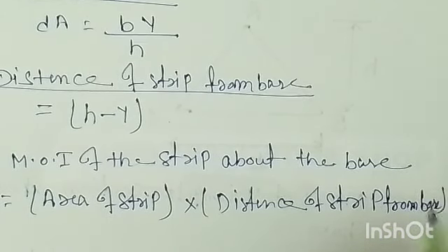Now when you multiply by b, first you can see that h to the power 4 is everywhere, so we can take it common and take it out. So this will become b h to the power 4 by h into 1 by 2 plus 1 by 4 minus 2 by 3, right? Now we can take the LCM. One h will get cancelled, it becomes cube, so it is b h cube, into the LCM which will be 12.